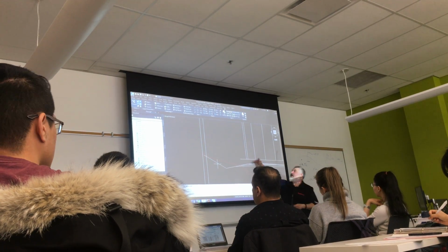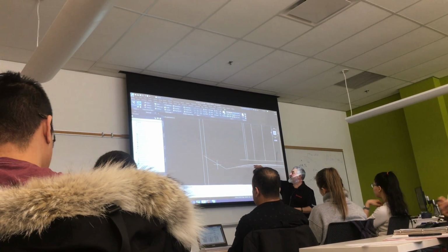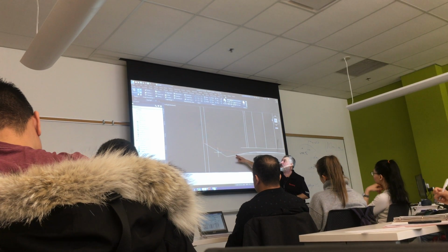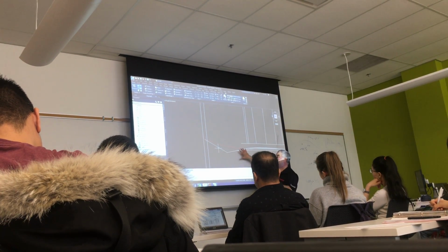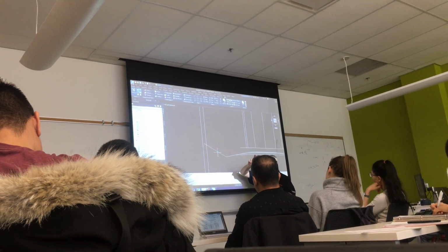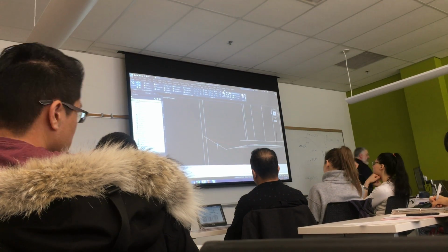And then draw your either side or fill slopes and extend the layers until they touch. If this point's underground, you have to continue down to the ditch and then back up. This is called a cut, side, and back slope. There's always 2 slopes. On the other side, it's a fill.